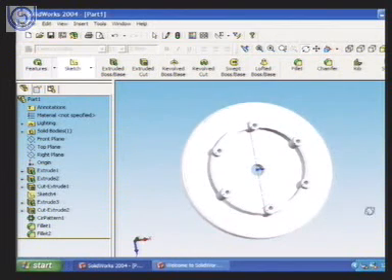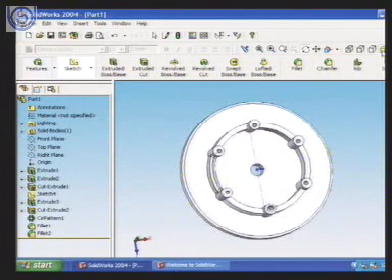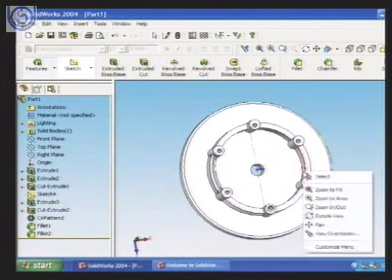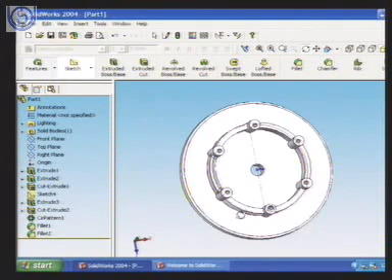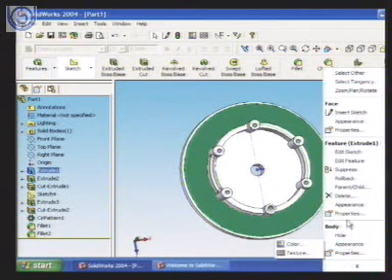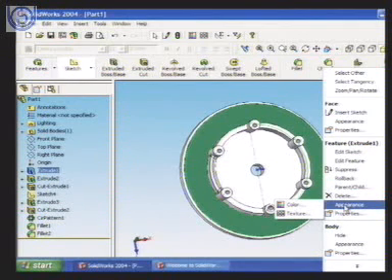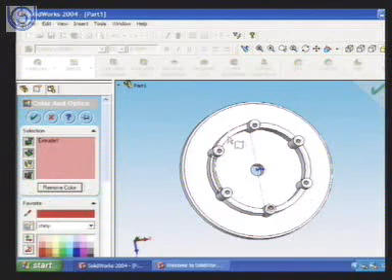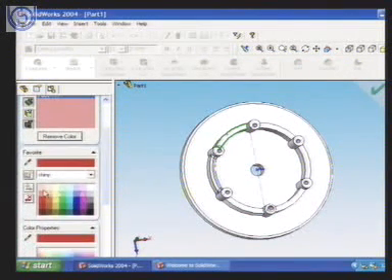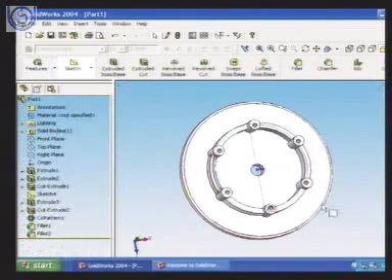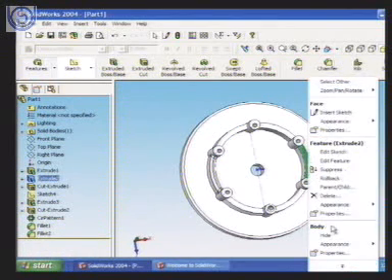You can see in the view, suppose we see here. If we select anything here, we can change the texture and color by going to the appearance. I say escape, the selection has gone. I go to appearance. This is the appearance. I say color. And I say OK. So why is it not going? Now I will show you why it is happening. Here I have seen feature extrude 2.